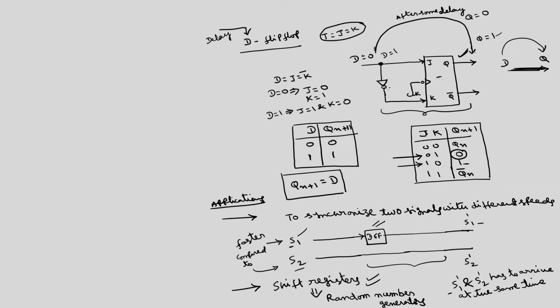So, I will start with a simple SR flip flop, because for a D flip flop there is no need for it to be edge triggered also. We can have level triggered D flip flops also, which we can use in shift registers. The reason is that in case of a D flip flop, the 1-1 condition never occurs. To get the D flip flop, you can use a simple SR flip flop. I will just discuss how a D latch can be obtained.